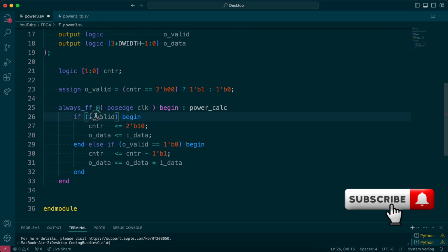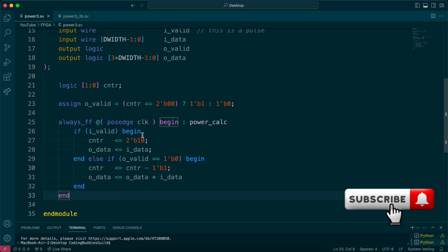Then I'm saying if iValid is 1, which means there is new data on the bus, then counter is set to 2 and O data is I data. Else, which means the counter is set and data is valid, let's do the calculation. If O valid is 0, and if you remember, we did it up here, O valid is 0 while counter is not 0. When counter goes to 0, O valid goes to 1. So while the output is not ready, keep decrementing counter and keep updating O data. This is how it works. Super easy.